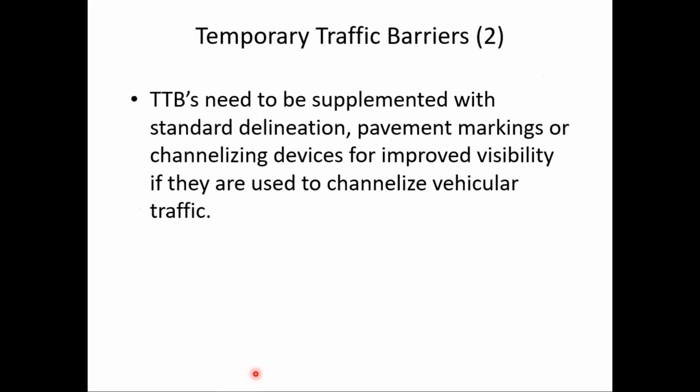Also, just keep in mind the temporary traffic barriers, since one face of them faces traffic, if you will, they need to be supplemented with standard delineation of pavement markings or channelizing devices for improved visibility, since they are used to channelize vehicular traffic.